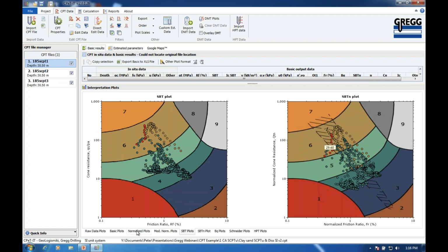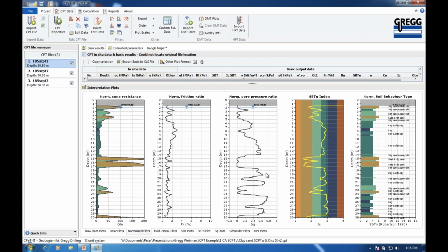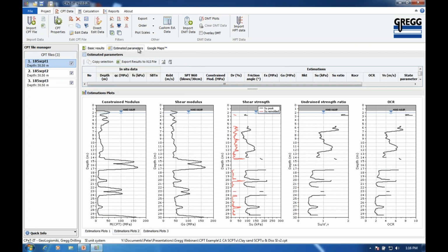If you don't want it to do it exactly that way, so here, for example, this upper clay is mostly falling into the clay-like region, which is why it's successfully calculating undrained strength. But there is a button up here that allows you to adjust that.